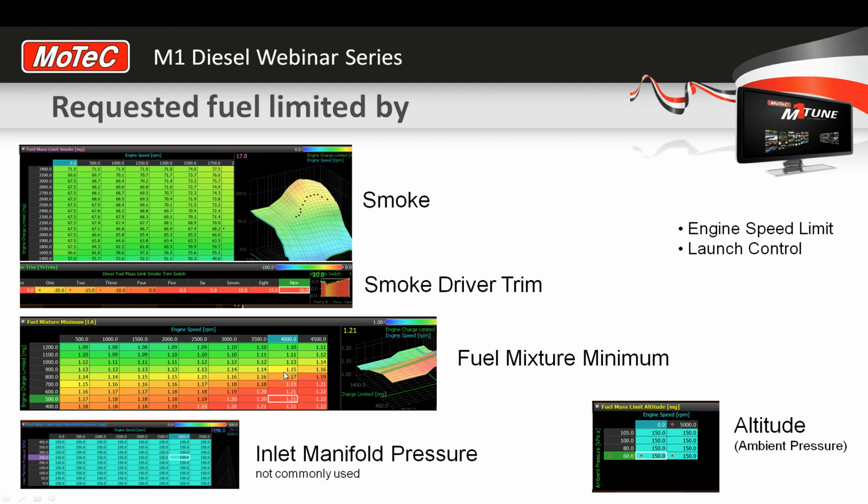So maybe a lambda of 1.15 at this point here: if we target a lambda 1.15, our lambda estimate would be 1.15, but we really want our measured lambda to be 1.2. Then we can put in the lambda number here that gets the actual lambda result we want. So they could be different.